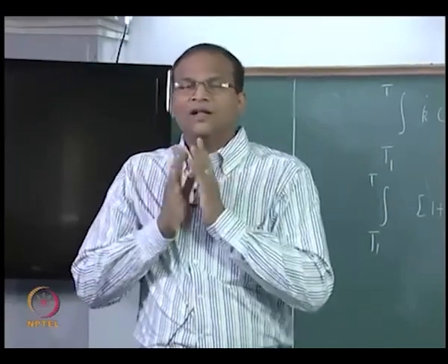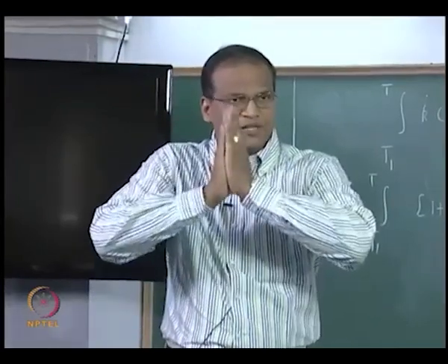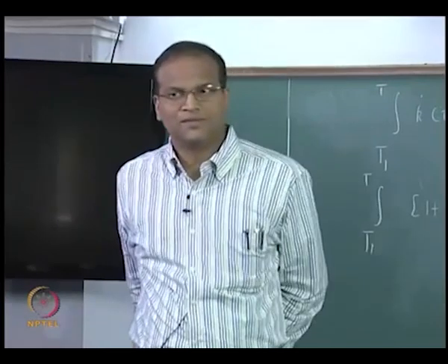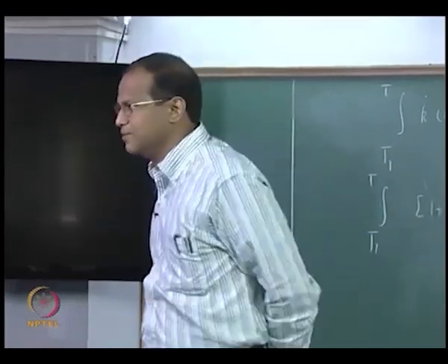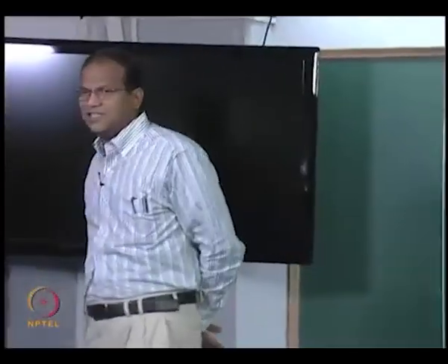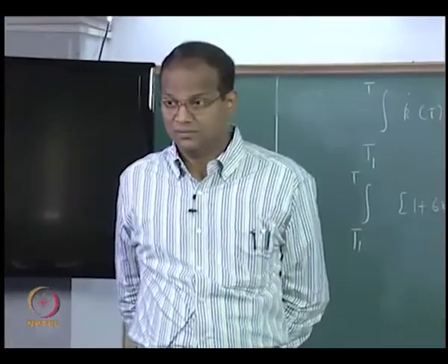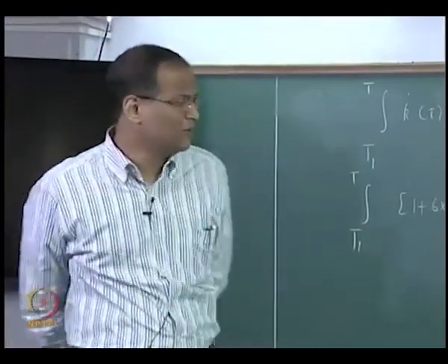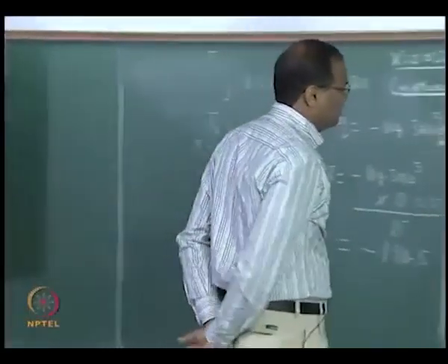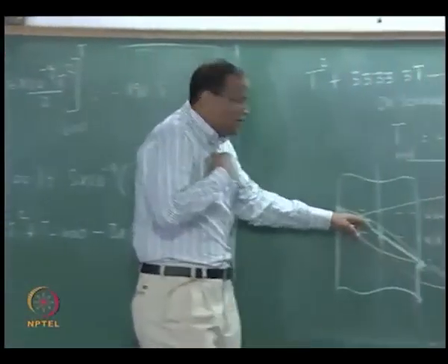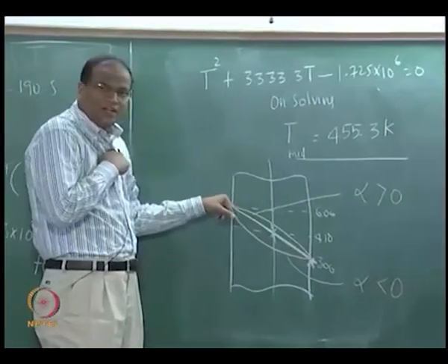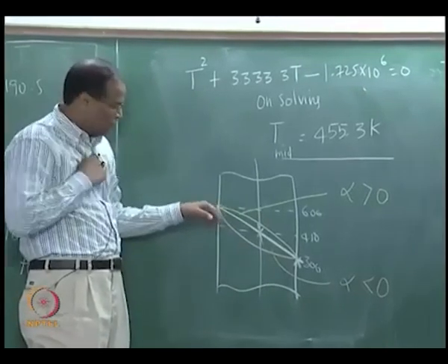The beauty is the linear temperature profile is disturbed. Now we have a quadratic or a parabolic temperature profile. It is consistent with the linear model for thermal conductivity, right. Alpha equal to 0 gives the linear model, fine. We got it numerically, we can also explain it intuitively, okay.